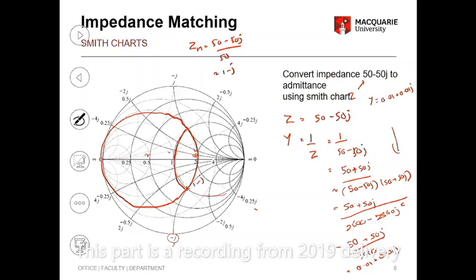Now I want to convert it to an admittance, so I will pick the conductance circle which has a 0.5. So conductance is 0.5 Yn, and then what do I need to do to get the susceptance? So I had to look at this curve, right? And it's 0.5 J, right? Guys following me? Or confusing? You're pretty much reading off two graphs, two Smith charts, on the same Smith chart.